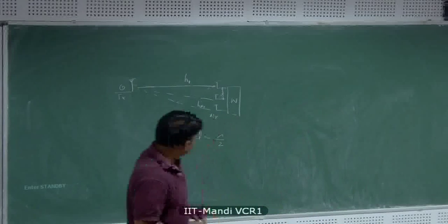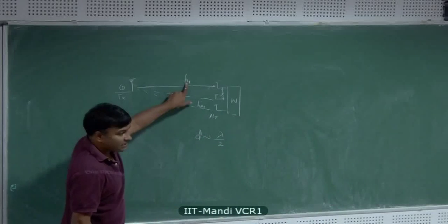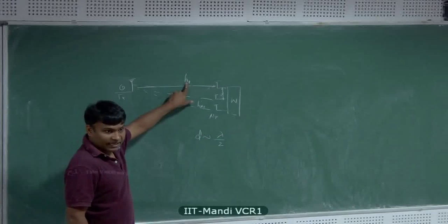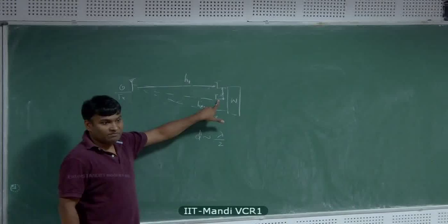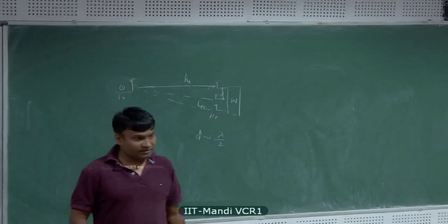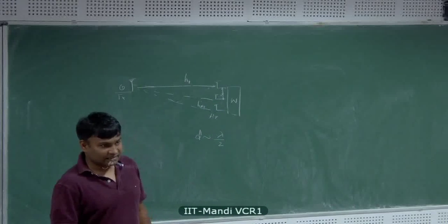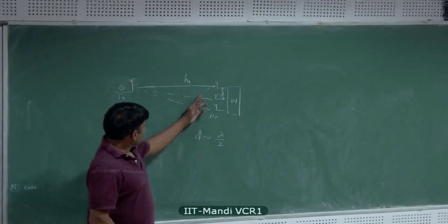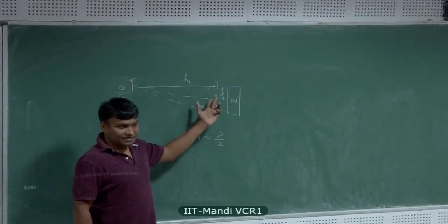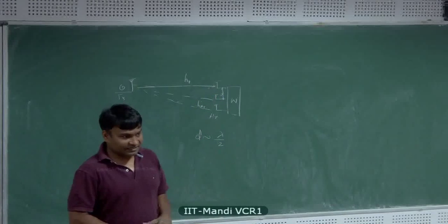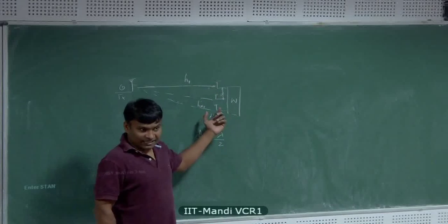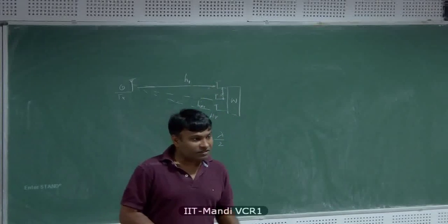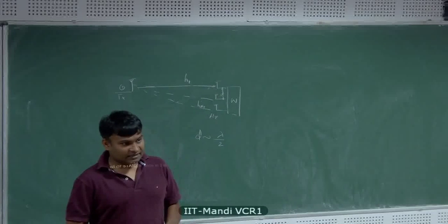The second benefit is, if one of these channel gains takes a low value because of fading, the signal received on the second antenna need not go through a deep fade at the same time, because they are statistically independent channels. That's how we model them. If that is the case, you can always choose the best antenna. You can always measure the energy and choose the one with the highest channel gain. That's called antenna selection, or selection diversity.